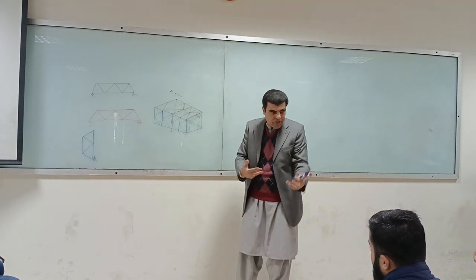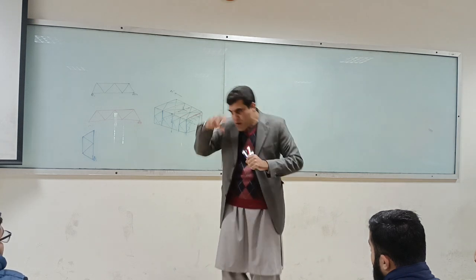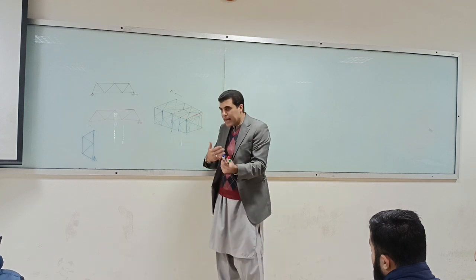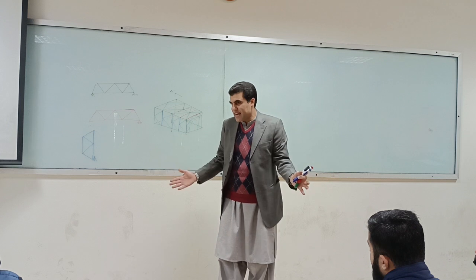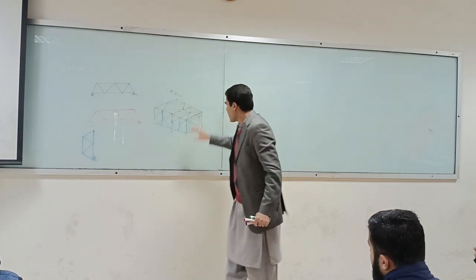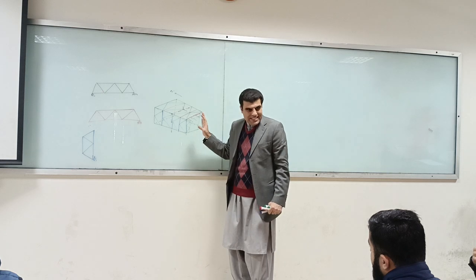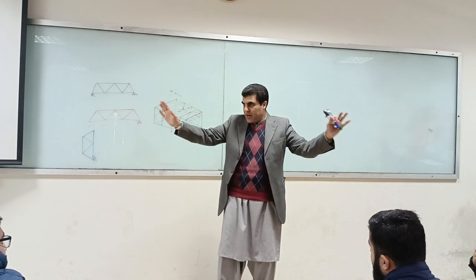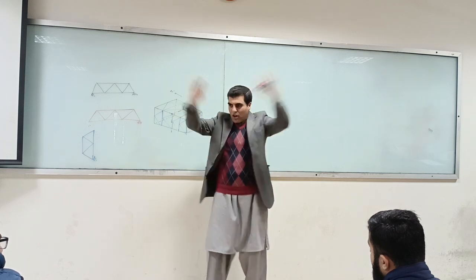What you want to do is to provide these braces. Again, look, you guys are engineers, so you have to think: where can I provide this brace so that I have enough space inside? The only place where you can provide your braces is the ends, and that's why in industries, right at the entrance, it's all covered.